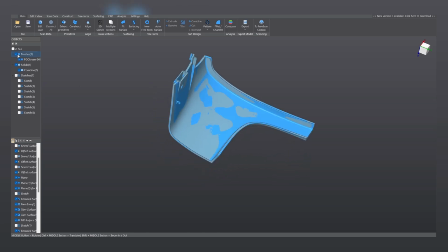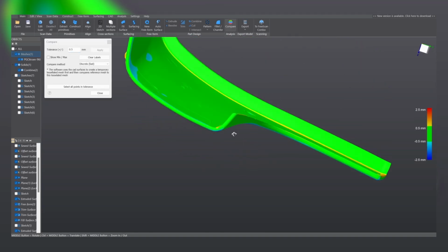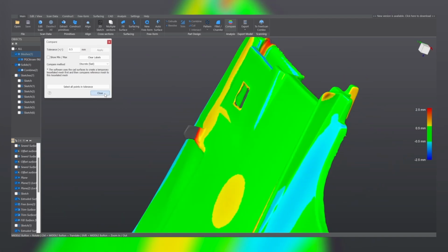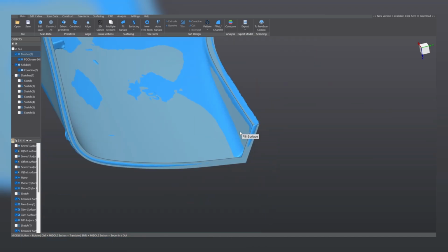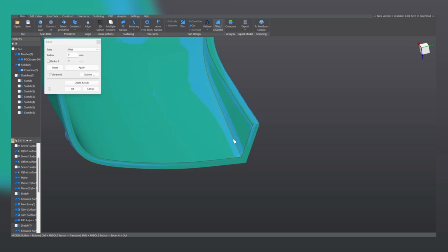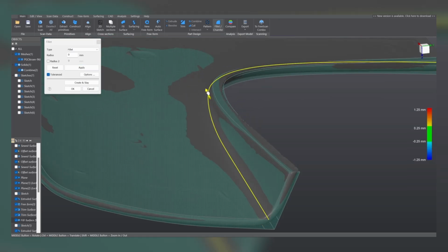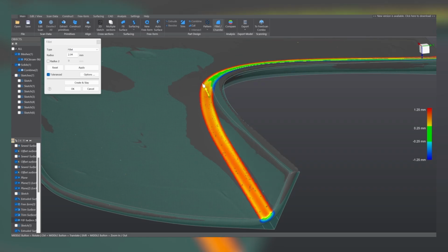And before completing the process, well, if we take a look at the comparison, we observe some errors here, right here, over there too, here as well. Well, the fillets are missing, and this is the last operation we would carry out. So to do it, just select the surface and click on fillet, and now you should be able to select the edge. And I recommend you to use the tolerance tool here. With it, you start dragging this arrow, and you can see live how the tolerances result evolves as you change the value of this filleting.